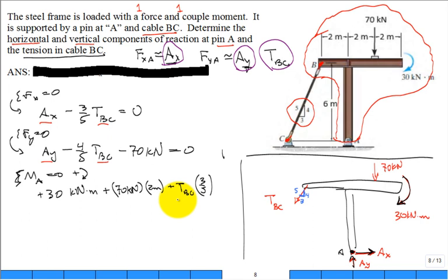And that 3/5 horizontal component has a moment arm distance of, you tell me, if I pick off the horizontal component, the 3/5 of the tension B to C, what's the moment arm distance? 6, exactly, 6 meters. Then I have to revisit the direction. So it doesn't make it want to rotate in the negative sense, because we put positive as clockwise.